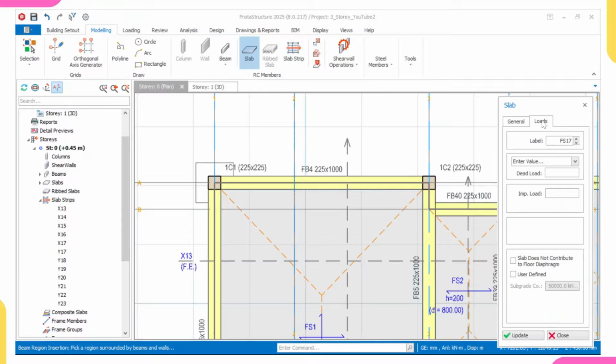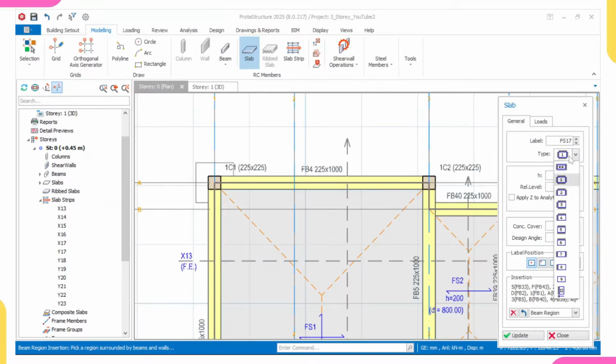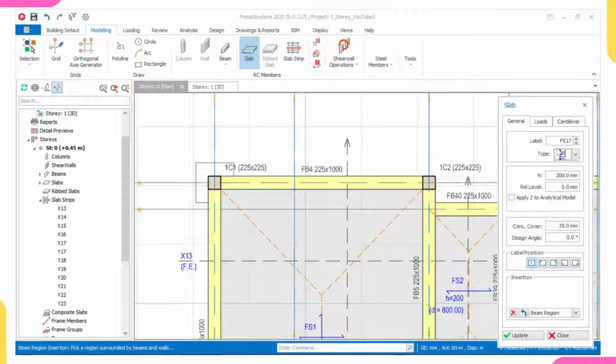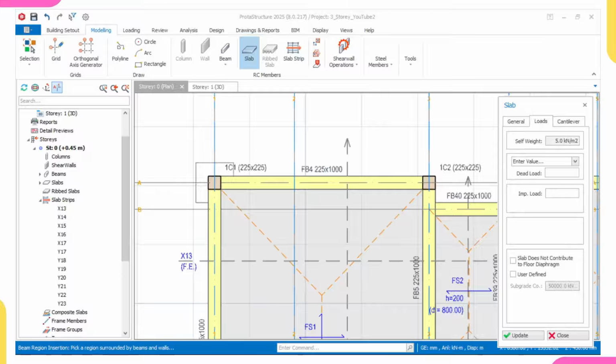Then coming over to this point, I'll pick cantilever length of what? 12. Then I'll leave the load. I will not apply anything on the load, because the only load I'll be applying here is the soil load, since it's only soil that will be resting on it. I can just choose to apply the soil load to be 0.5. Then I'll not apply any other load again.